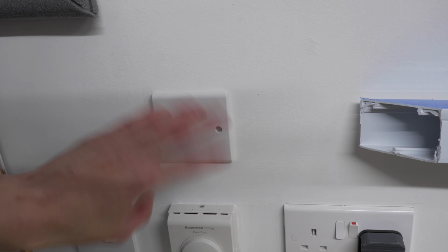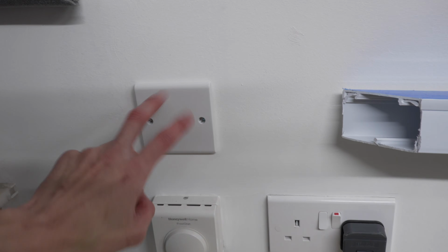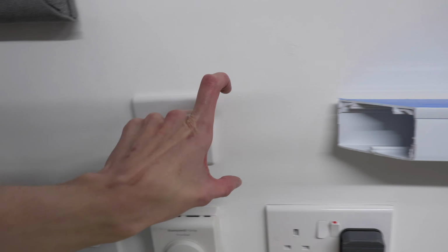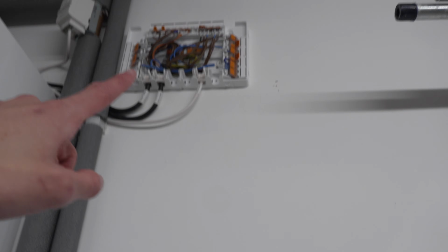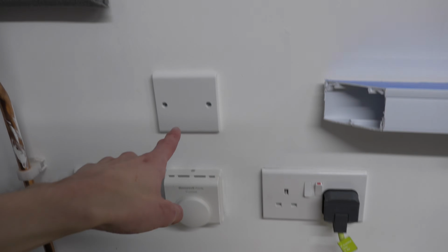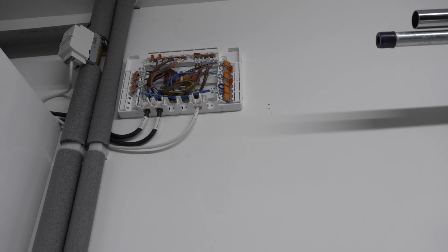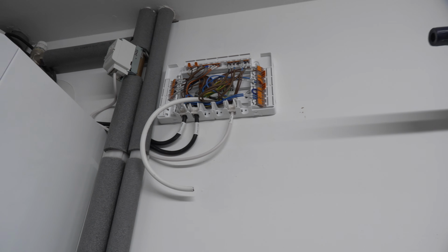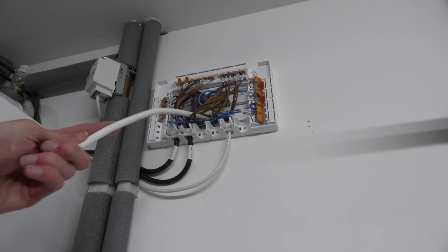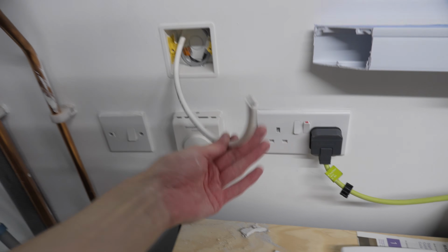So what I'll do just now, just to mount the Wiser hub in a neater place, I'll take this off and I'll mount the Wiser hub over this, and then I'll run a 5-core flex from here up through inside the wall into this wiring centre, just so the cable's completely out of the way. We'll have the Wiser hub down here, and then it'll all connect to the wiring centre. So I'll get that cable installed, and we'll take a look at how it's all connected up. And there we go, so I've now pulled in a 5-core flex up here into the wiring centre, and that runs straight down the wall and comes out this box here, and we've got the cable here.